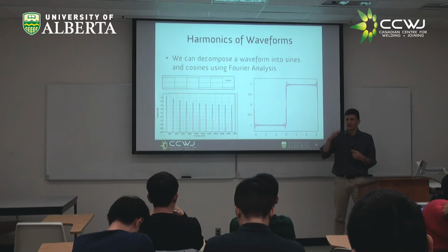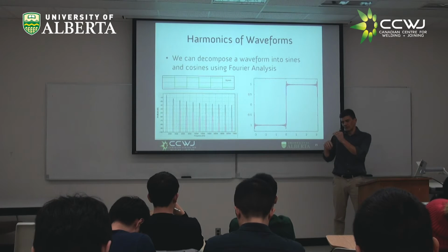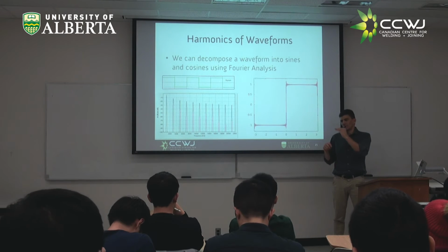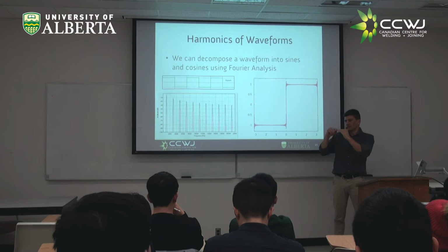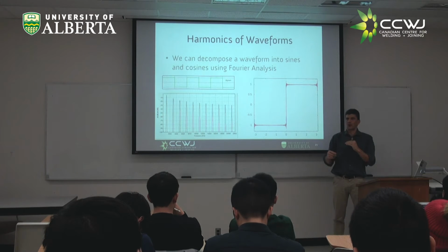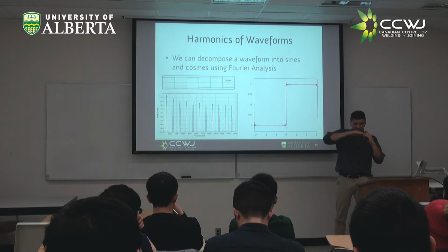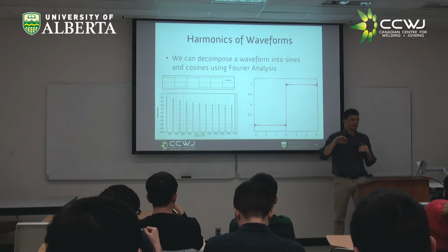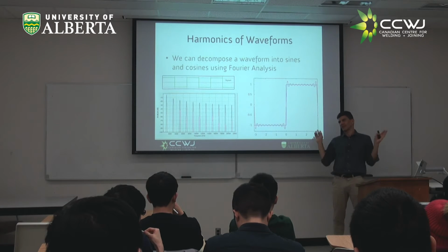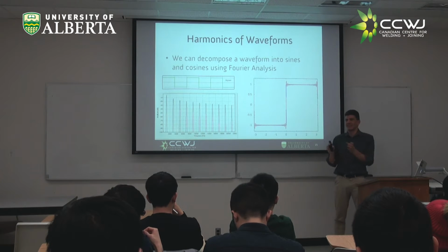If you have a square waveform, it goes from, I don't know, minus 30 volts to plus 30 volts, or minus 200 amps to 200 amps very quickly, passing through 0 very quickly. If you have a sine, it goes gently and passes through 0 gently. Well, if you pass through 0 gently, the arc might decide, okay, I'm done. And that's the whole story between 6010 and 6011.